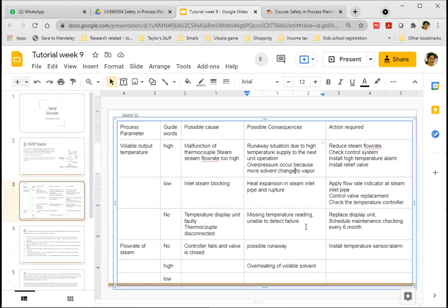This one is hazard analysis. You can use this one, or you can use event tree, fault tree, which is in the next 2 chapters. I have already opened all the chapters so that you can start viewing them first. And if the factories or the case that you took up deal with chemical storage explosions, you may want to use some of the information over there and recalculate how much chemical they actually store and how much is allowed. These are all the calculations that you can use in that section.